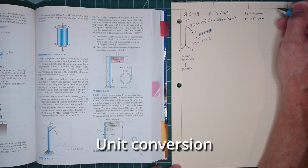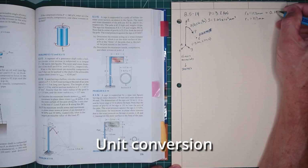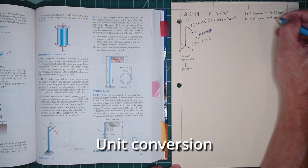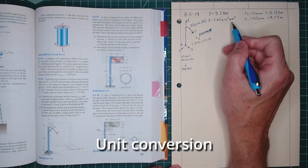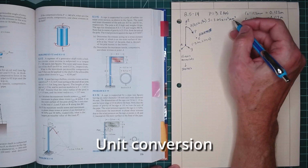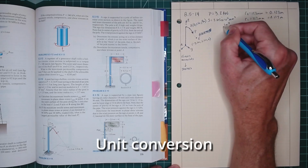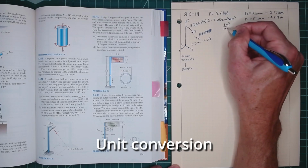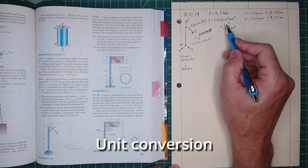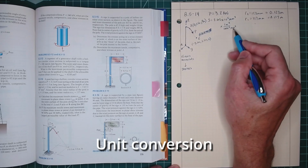So my radius here, 123 millimeters, is 0.123 meters. Our other one is 0.117 meters. The other thing we need to do is convert our section modulus. For converting millimeters cubed to meters cubed, we multiply by 1 meter cubed per 1,000 cubed millimeters cubed.